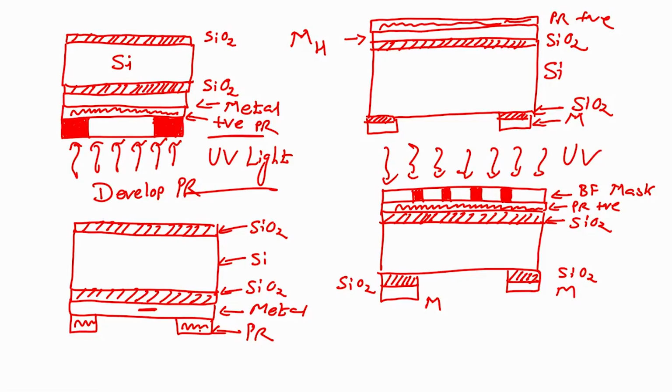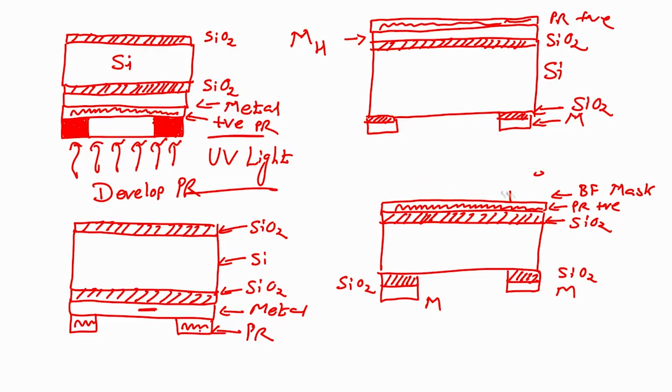When I expose it with UV, after exposure I will unload this mask and I will dip the wafer in photoresist developer.